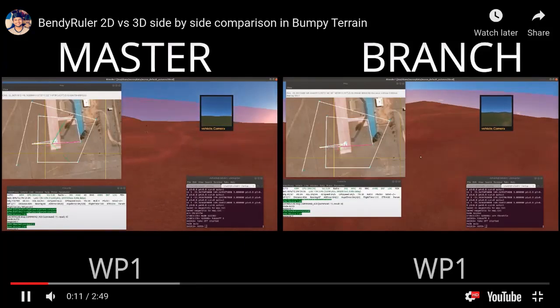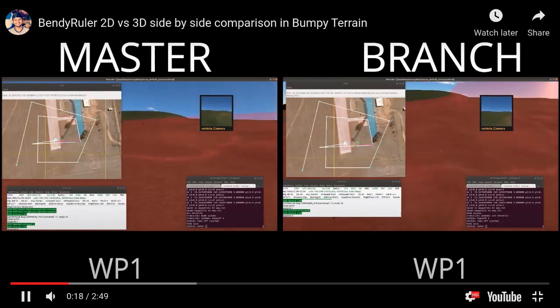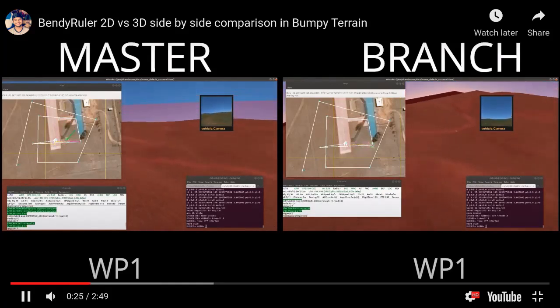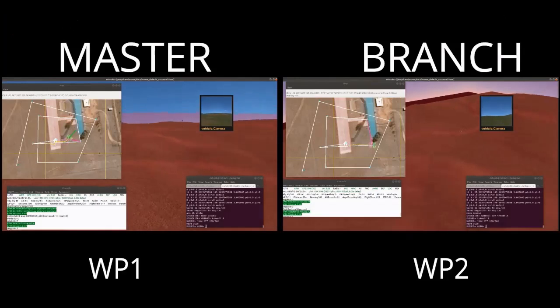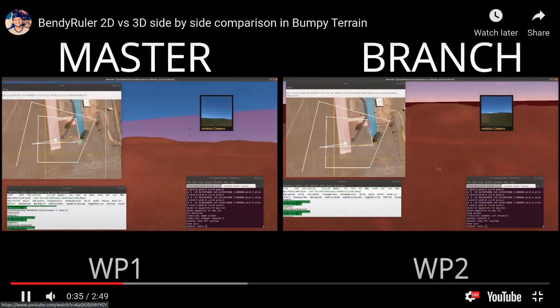The difference that it makes is that this is again Morse, with Copter 4.0 on the left and Copter 4.1 on the right. You'll see that the vehicle on the left keeps avoiding random obstacles which were actually down below and not in front of it. But the vehicle on the right is traveling smoothly. It has no problem at all. And this is a low altitude flight, like 2-3 meters.